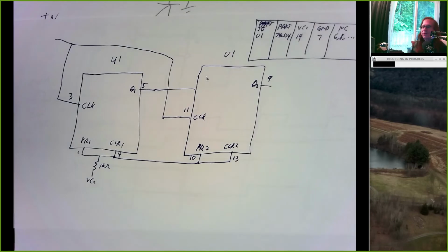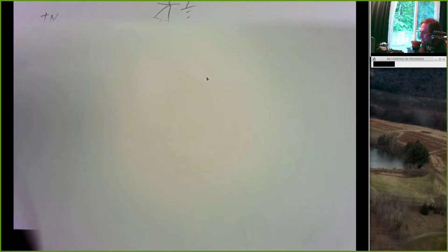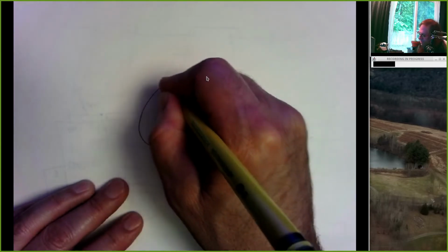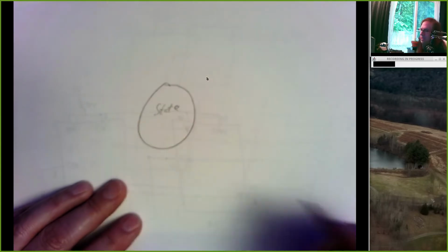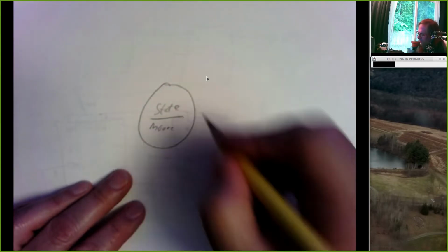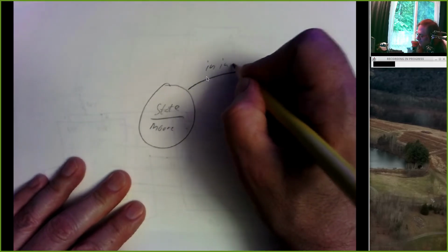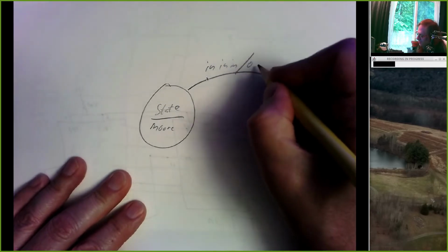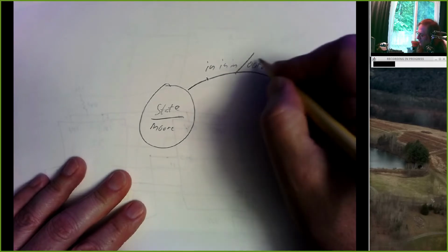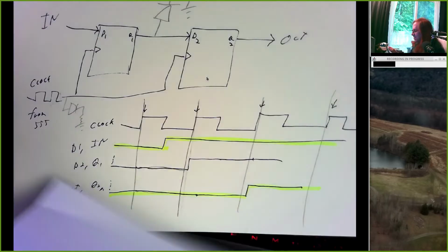If you're talking about the key in our state diagram, that's different from all of this, right? I'm drawing a picture that shows the state. And if there's a Moore output, you can list that here, and then show the transition arrows and the different inputs slash your different Mealy outputs, the outputs that depend on the inputs. So that's the state diagram key.